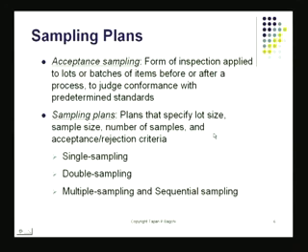And I should just tell you that all of this is based on inspection of a limited amount of products that you pick up. So from the lot, I just picked up a small sample. And on the basis of the results of inspecting this small sample, I'll decide the fate of the full lot that has been supplied to me. So really it depends on the performance or the quality level of the two or three parts that are in the sample. I'm going to be deciding the fate of the full lot based on the performance of these sample items. That's what I'm going to be doing.